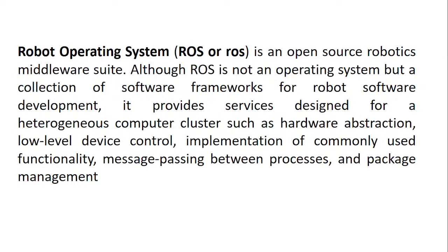Then wheel odometry sensors, or wheel encoders, are simply tick sensors. With each rotation they register one tick, so that we can count the RPM of the motor in real time, and also the direction in which the wheel is rotating. Using that we can know how the robot is moving, in which direction, and at what speed.